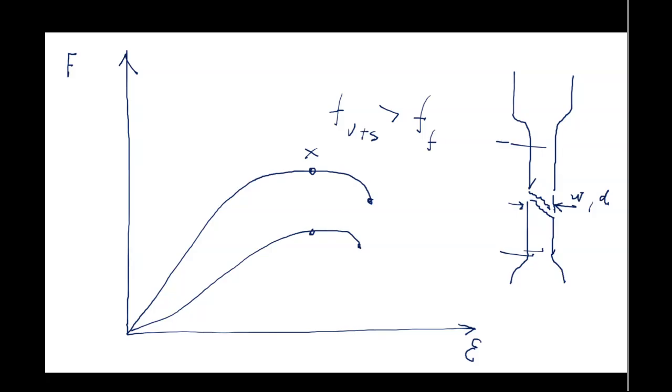The gauge length at fracture is needed to then work out the strains for both materials. And the cross-sectional area is also needed to work out the percentage reduction in cross-sectional area. This is what the necking will give us. And the changes in gauge length will also give us the percentage elongation. So most of you have managed well, and you got really reasonable data.